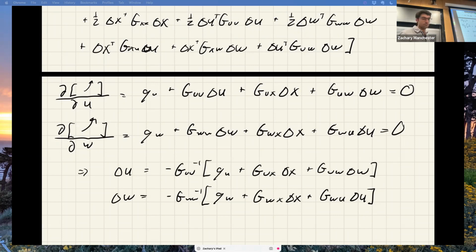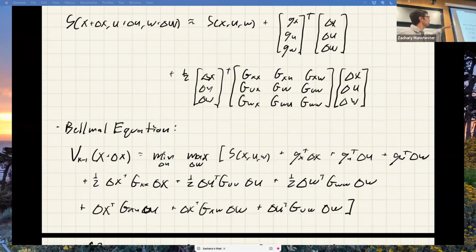And ultimately what that comes down to is, if I look up here at the action value Hessian, the parts of the Hessian corresponding to the X's and U's up here, these guys need positive eigenvalues. And the part corresponding to the disturbances, this W guy, has to have negative eigenvalues. So that's what it should have.